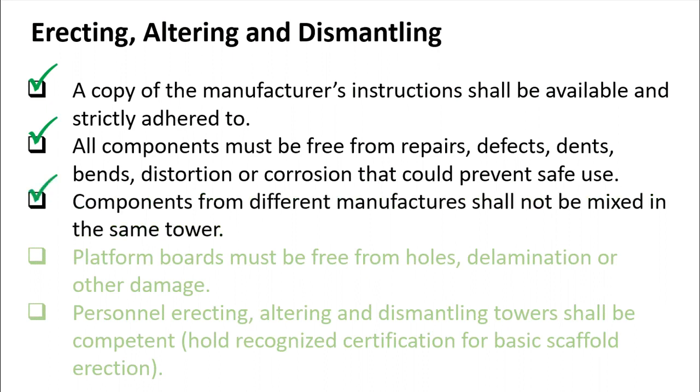Components from different manufacturers shall not be mixed in the same tower. For example, you have one whole scaffold of one manufacturer, and then you have a missing brace, so you get another component from a different manufacturer, which has less capacity or safe working load.